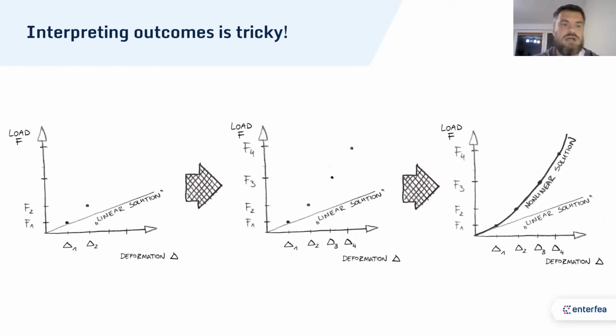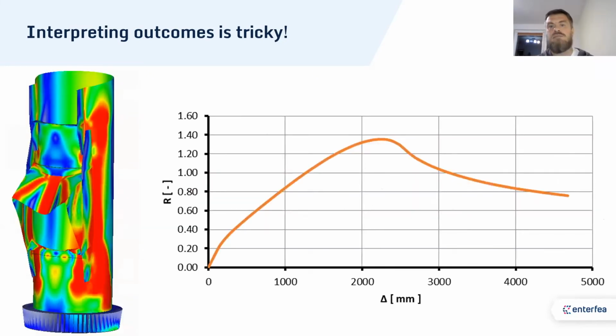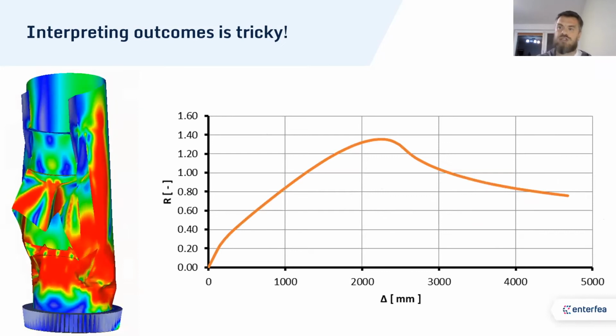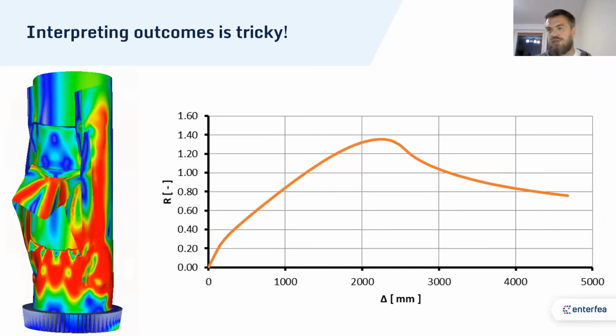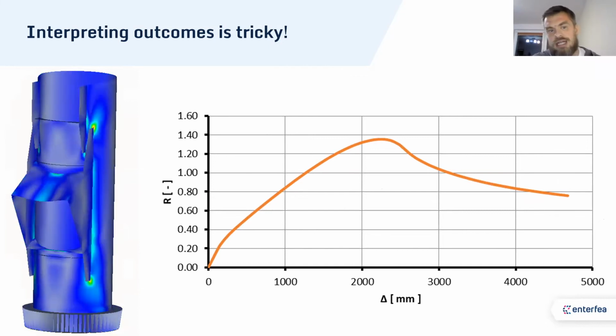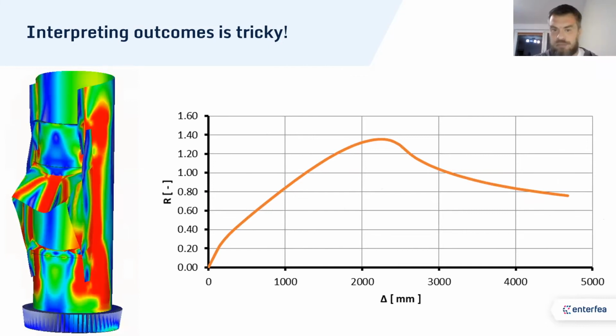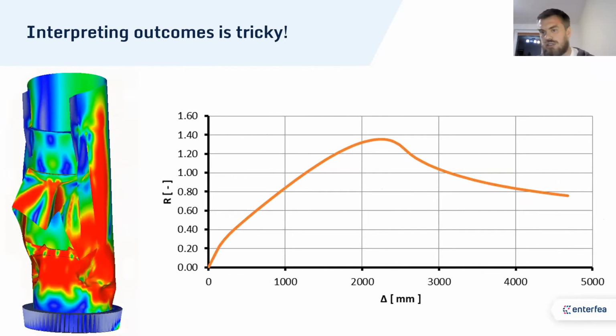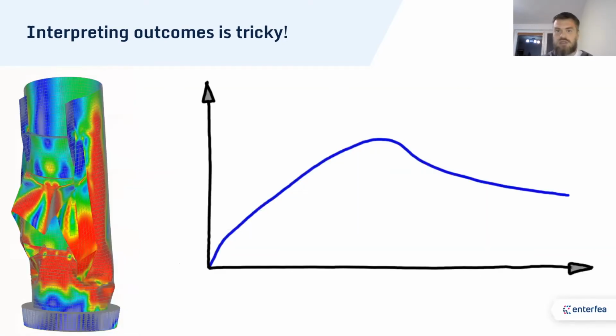If you wonder what is linear or nonlinear in FEA, this is the line that is linear or nonlinear, essentially. That's the one, right? So if I would use, for instance, a beam that can enter membrane state, it will strengthen. So I would have to press more and more to cause deflection, and the curve would not be a straight line anymore. And a line measuring applied load versus the deformation of the tip of the chimney, in our case, looks like this. You can see the animated outcome of the model and how the chart looks. And I will just switch to the drawing one because there are a few things I want to show.